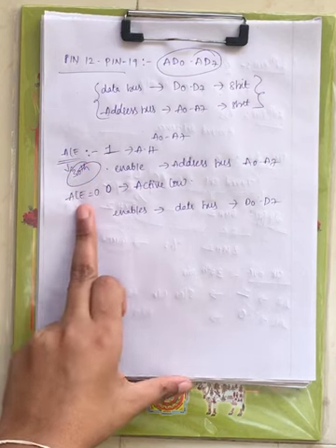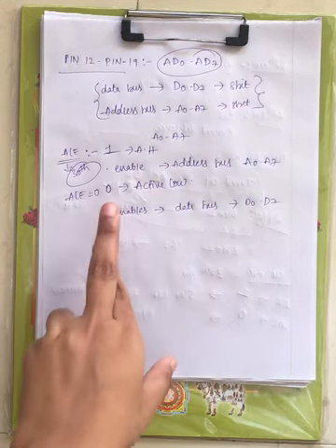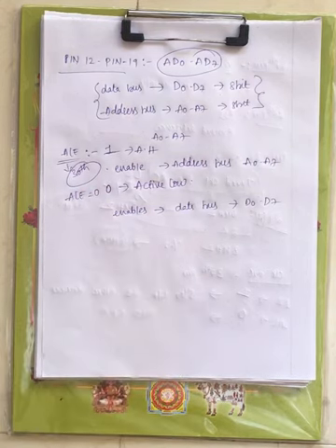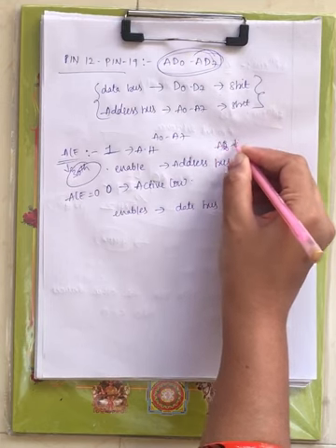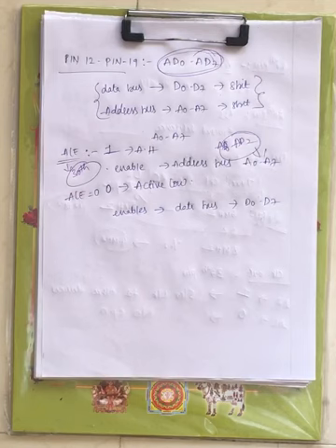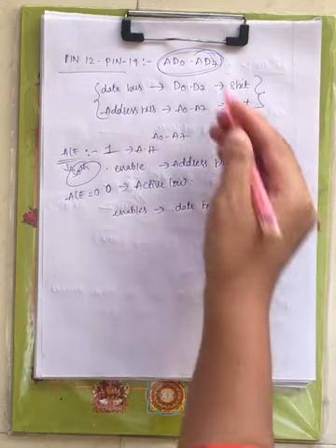When it is active high, that is when ALE is 1, you can carry the lower order address through AD0 to AD7, that is A0 to A7. When address latch enable is 0, you can carry data bits through these lines.